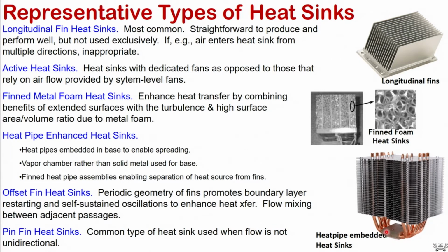The heat is spread or carried from this. In this case, for example, in the picture shown here, there are these four heat pipes, and this is where the heat is generated. The heat is delivered from this point to this place, where the air is flowing, and there are lots of parallel plate fins. The liquid to vapor change is happening, the vapor gets condensed, and the condensed vapor returns back to this heat pipe, to this heat source itself, by natural capillary action and also by gravity in some cases.